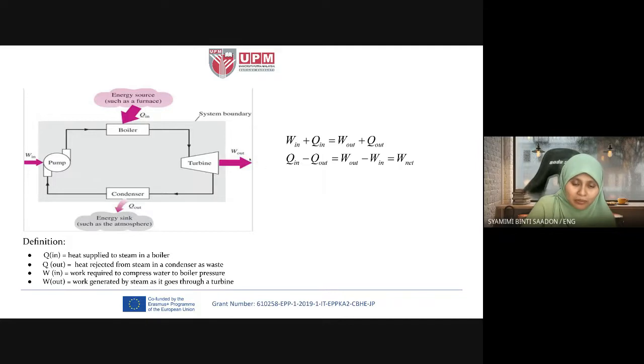The energy that we are going to produce, the electricity or the mechanical work. This is our desired output, and then the working fluid will continue. We complete the cycle by entering a condenser. The condenser is the opposite of the boiler. This is to evaporate, this is to condense. Just the opposite function.